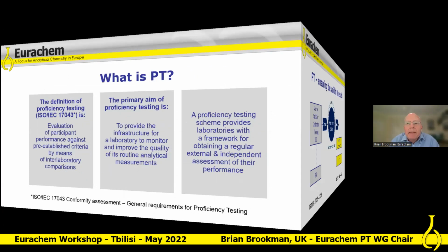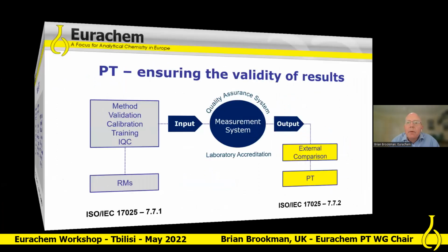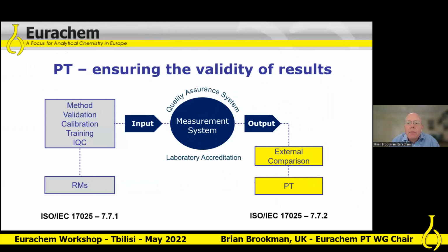So I've already mentioned that PT is key for ensuring the validity of test or measurement results. In any laboratory, the measurement system needs to be appropriately set up if it's to make reliable measurements: the methods need to be validated or verified, the instruments calibrated, the staff trained, and some form of internal quality controls implemented. And this is very much what I would call the input measures within the laboratory, which we link to those input quality assurance tools as required by 17025 in clause 7.7.1.